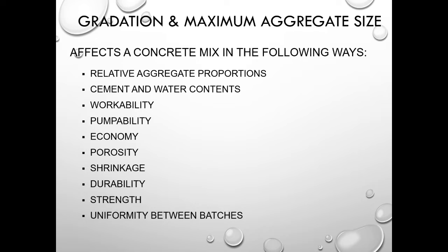Can we pump the concrete? In other words, we're going to design a concrete mix if we know we're going to place it with a pump. Again, gradation and the size of the aggregates are important in coming up with a good pump mix. Economy. Obviously, money always comes into play. Porosity. How porous is the mix? Okay, are we going to have a good dense mix with small voids or hardly any voids?